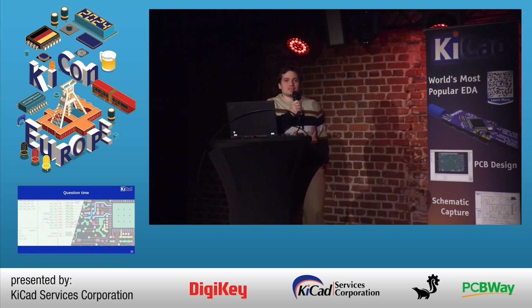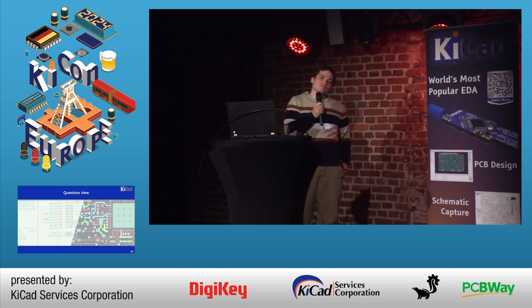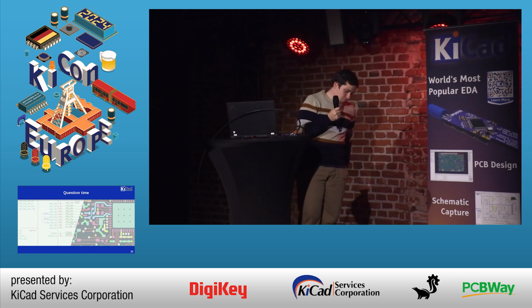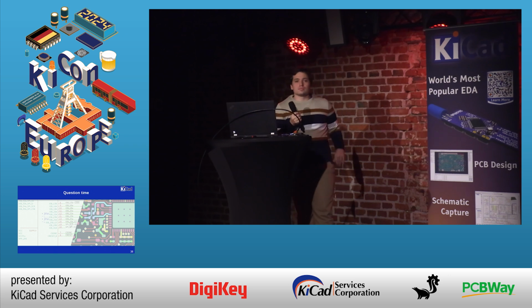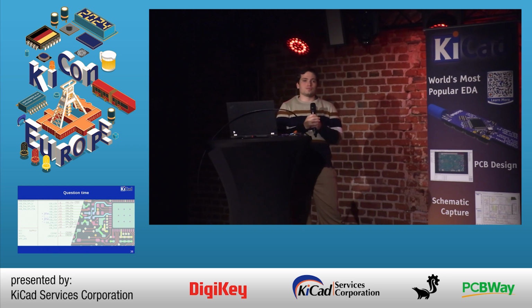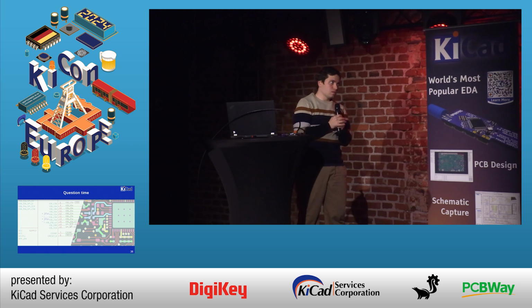And the second question, is it possible to check creepage or set minimum creepage within the same net class? Because in the matrix you showed, there was net class 1 to net class 2, net class 2 to net class 3, and so on, but there weren't net class 1 to net class 1. And maybe the same for the clearances.